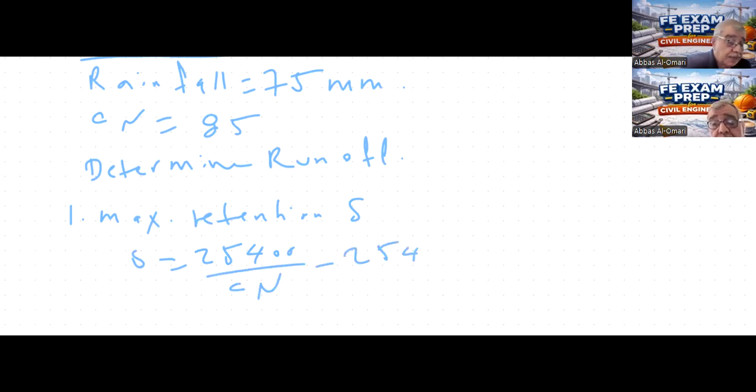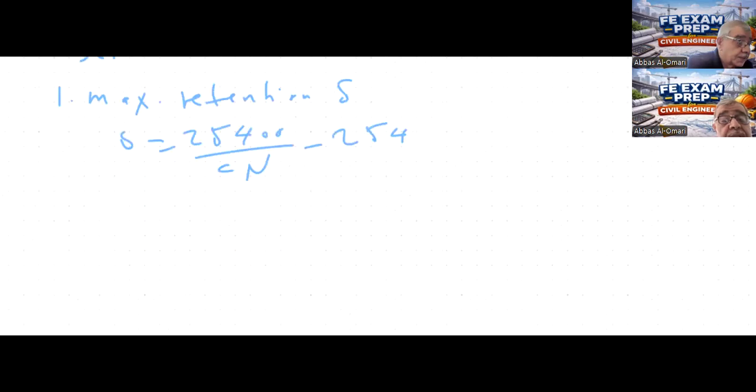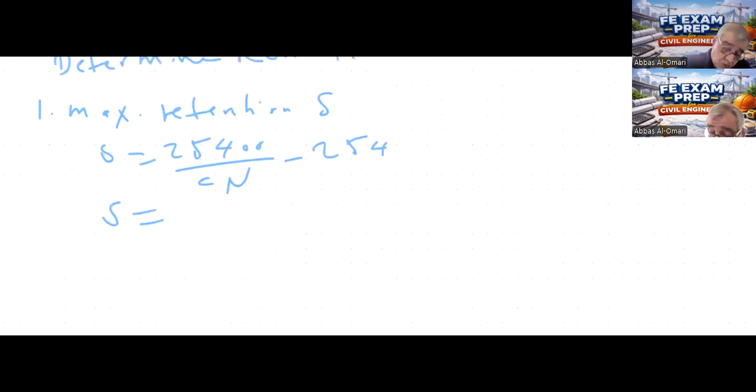We know the curve number is 85, so we substitute 85 for the curve number and we get S equals 44.82 millimeter.